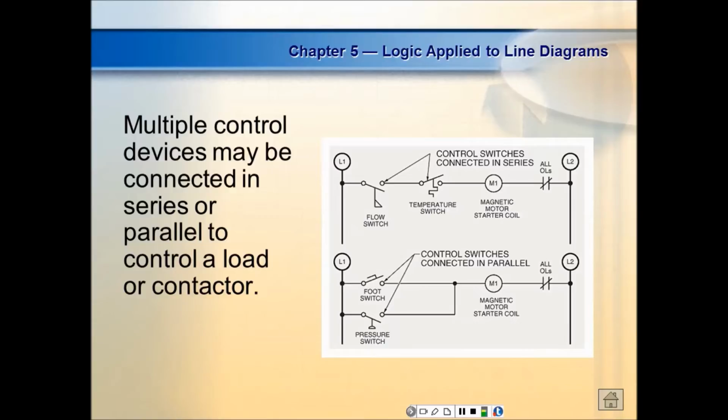But what we're doing here, to energize this relay right here, that magnetic motor starter right there, what do we have to do? The flow switch has to be closed, and the temperature switch has to be closed. You hear what I said? What did I say?